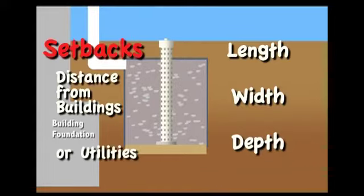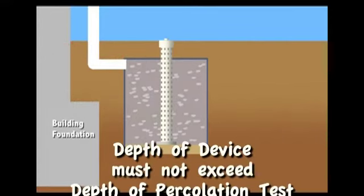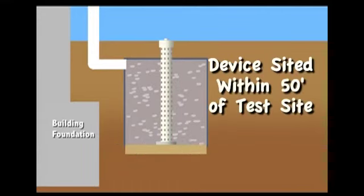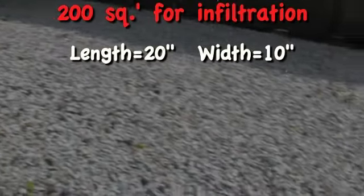These are called setbacks. For example, 20 feet long by 10 feet wide by 5 feet deep. It's important to also remember that the depth of an infiltration device cannot be deeper than the original percolation test and must be within 50 feet of the test. A trench this size would have 200 square feet of surface area available for infiltration.